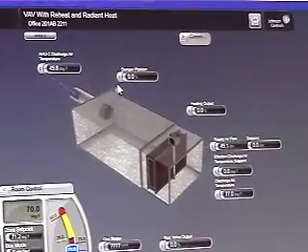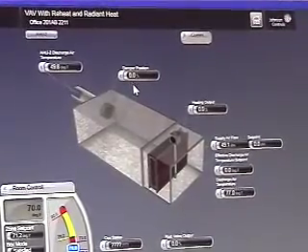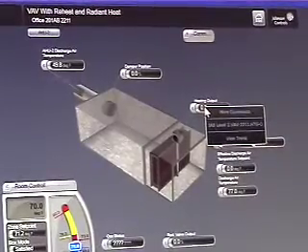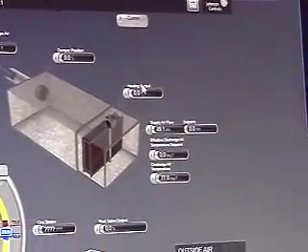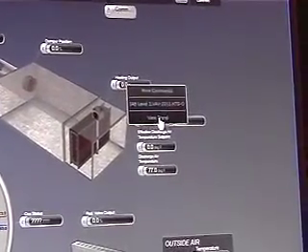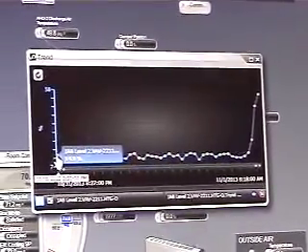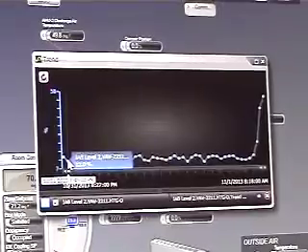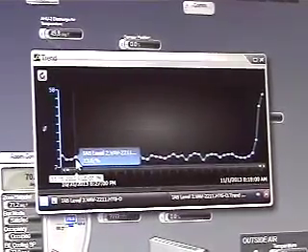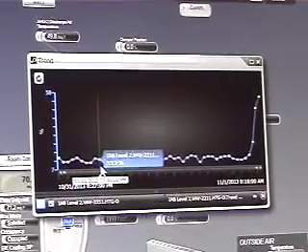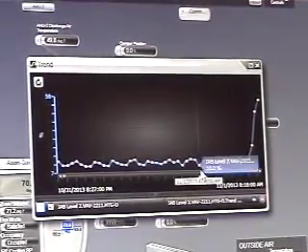From here, you can also look at trends. Let's see, I don't know which one. Here's one right here that has the trends on the heating output. Same thing, if you just right click on it, you can hit view trend. And it's going to give you whatever's in the repository. So generally you'll get about 24 hours worth of trends here. It allows you to look at a snapshot. We've done them every 15 minutes. You can look at them that way.